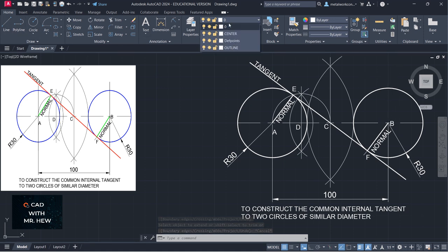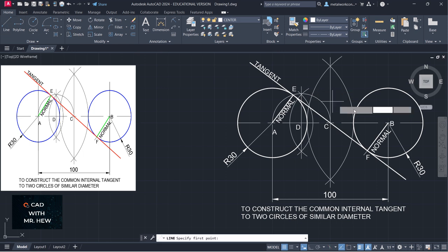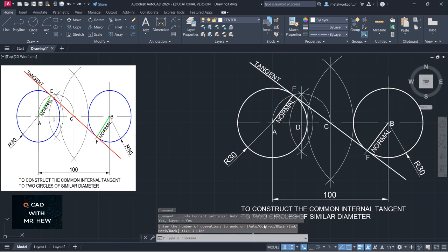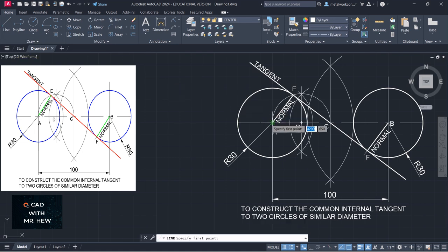All right, the next thing you need to do is draw the center line going above. So we're going to go to our center layer, line, going to turn on object snap, unsnap, enter. So we go again, we go line, from there to there, enter. And then we're going to make it smaller. So we're going to click this and come down. Going to turn off snap and object snap. Come down. Good. Right?